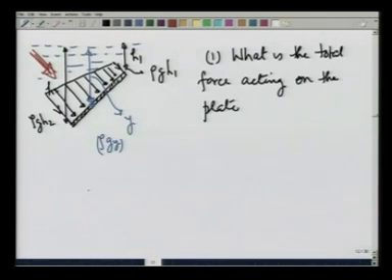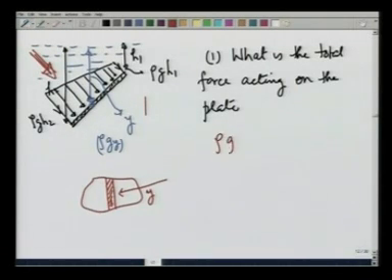Then you will see the plate could be of this shape. If I take a particular area here at depth y, and I am measuring depth from this side, then the force acting on this area is going to be rho g y dA.